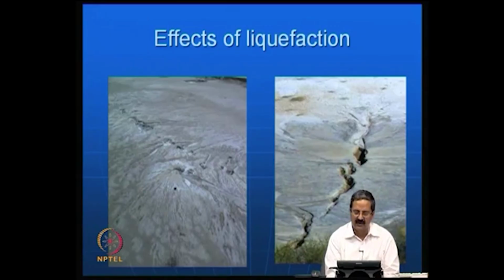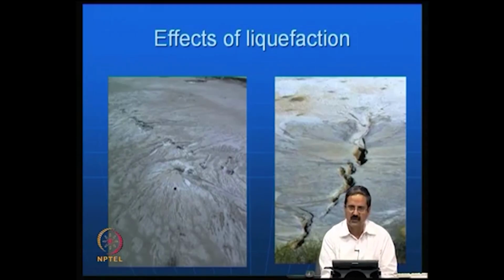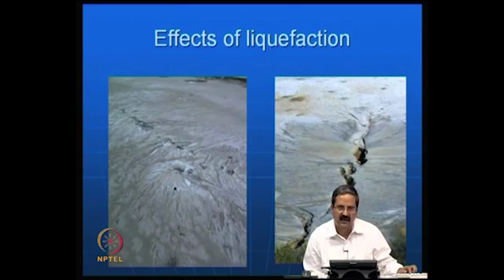We are familiar with what is called the quicksand condition, where the material can get sucked in. That happens because the earthquake force is so high, and the water is not able to come out. Under those conditions, if you have any building, it gets totally into the soil. In fact, Chang Dam, one of the dams in Gujarat that failed, is a classic case: it was founded on liquefiable materials, and it totally sank into the ground. Fortunately, it has been rehabilitated now, and it is satisfactory. They used some ground improvement techniques to rehabilitate that area and then reconstruct the whole dam. This is one classic example.